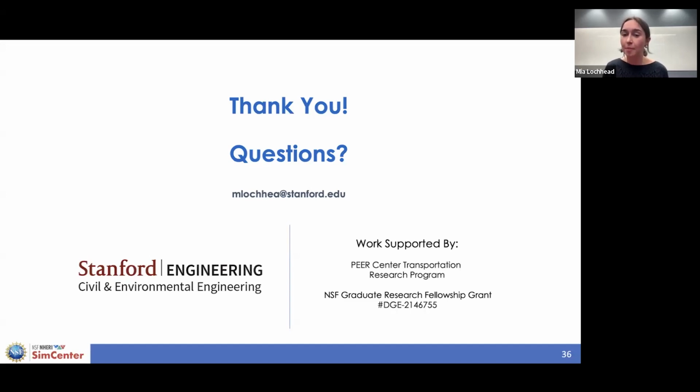These are all recorded, but not constrained to California. I think it could be an interesting direction in the future to use synthetic ground motions because you have a lot more control over what your ground motion parameters can be. By using real ground motions and just sampling things like SA ratio and duration, we're losing information there. We're not using the entire ground motion time history for our predictions, and so that's definitely causing uncertainty in our models. So if you do have these really specific recorded ground motions, you can get a lot more information extracted out of that and a lot more control, which could lend itself really well to surrogate model development.